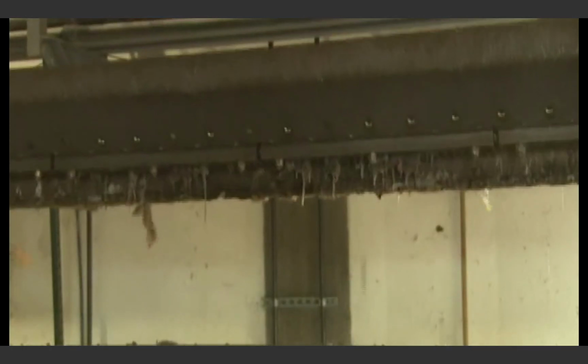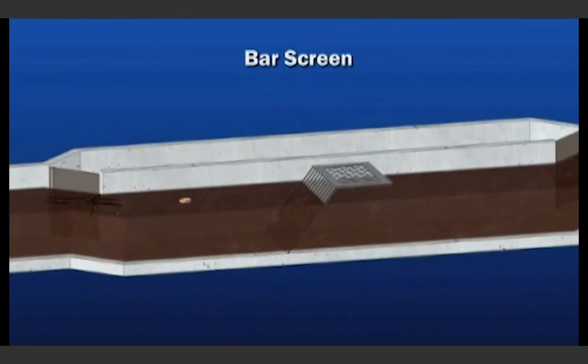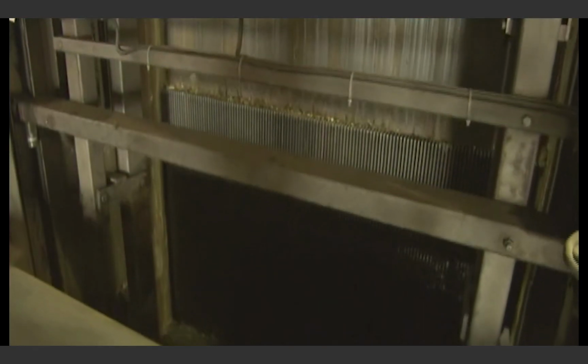Wastewater entering the treatment plant, or influent, flows through a first step called preliminary treatment. This step removes the solids that could damage pumps and clog pipes and cause undue wear on equipment. The preliminary process consists of screening, grit removal, odor and flow control, and equalization. Screening removes large objects such as rags, sticks, plastics, and rocks. Bar screens, drum screens, or passive screens are the most common.